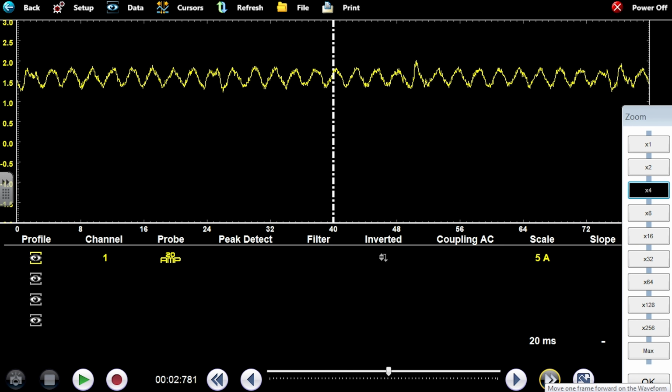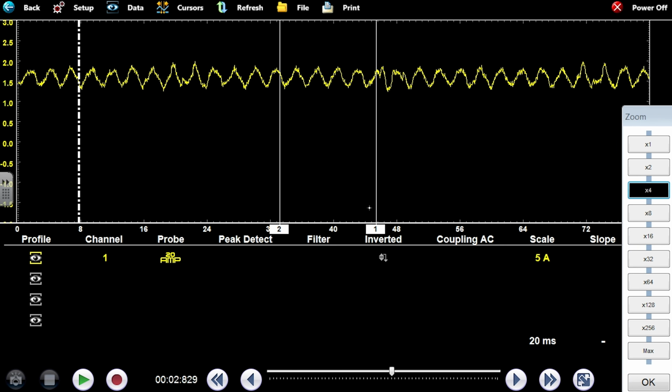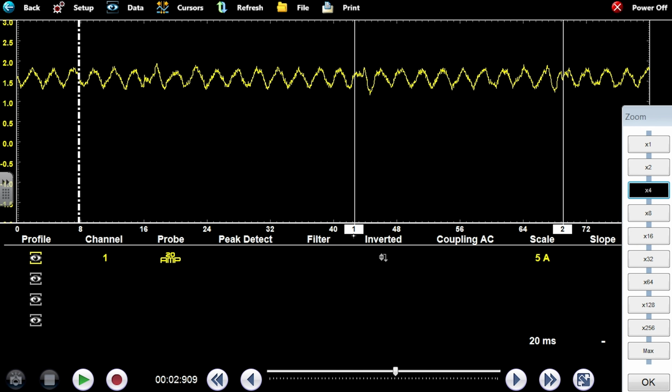You look at this waveform, they're tough to pick out sometimes as far as repetition of the signal. We could look at that weird one and look for it again. I don't see it. Let's go to the next frame. See if we can see some repetition here. This one here looks like an M. It kind of looks like that one there. What do you think? Yeah. So then you count your humps in there. Typically it's 8. 1, 2, 3, 4, 5, 6, 7, 8, 9, 10. That'd be a 10-bar pump.